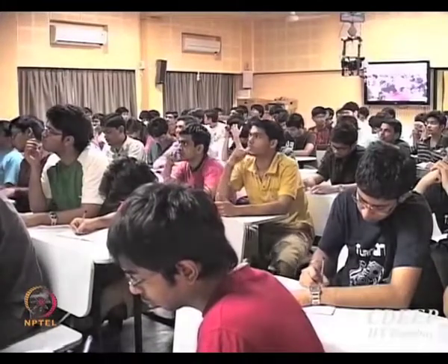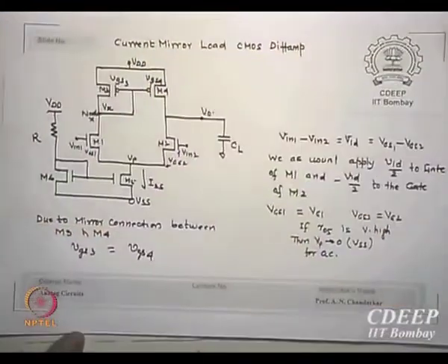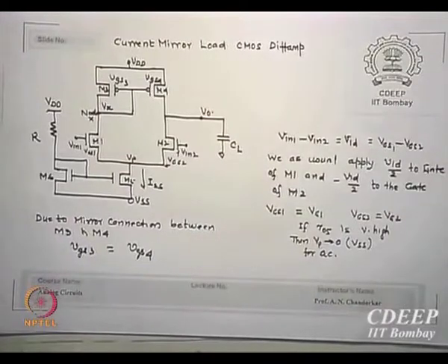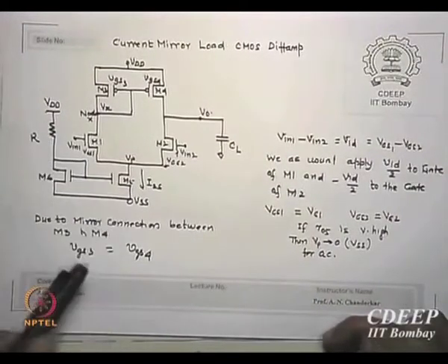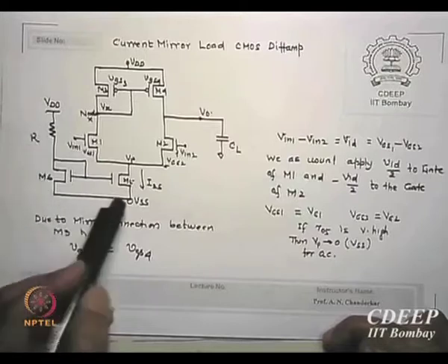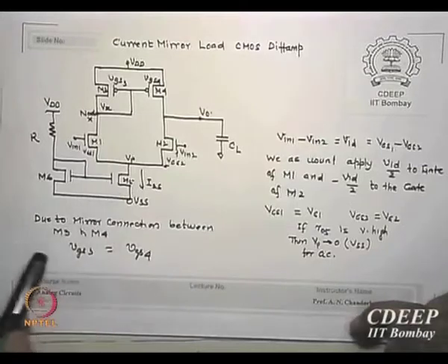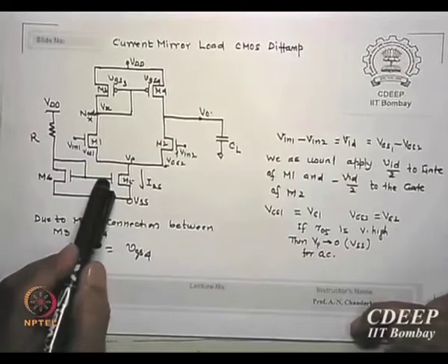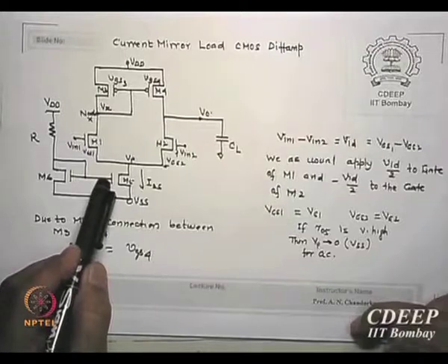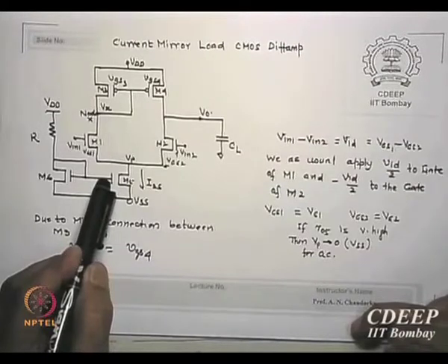Now here is something which the real circuit may look like. This is your current mirror. So the current ISS is created from where now? Please remember the difference from the last stage, where I applied some potential VGG here to get that current source. Is that clear? In the last case I applied a supply voltage to M5 and got the current source out of it.